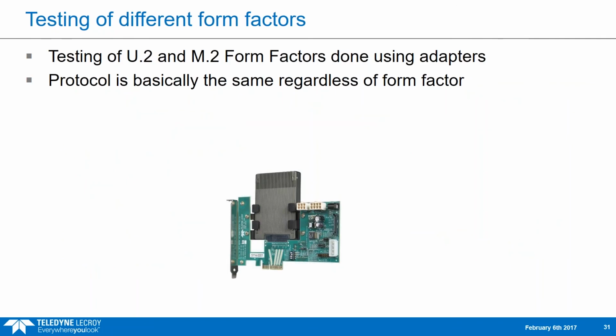One other point here is that you do need to make sure you use the correct cable for the T34 to the test platform, and it has to be the one that includes the SM bus connection. And that's a blue cable rather than a black cable. So the test cases are all held in the software, so you can select the test cases. I'll show that in a moment.